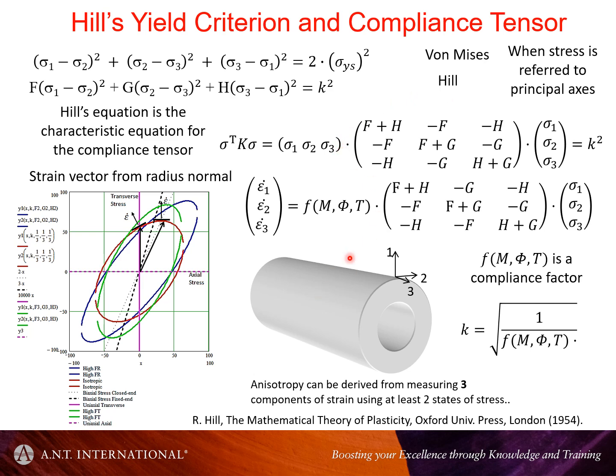And from that, we can calculate what the strain rate is, because one of the characteristics of a tensor property is that, if we're in stress space, wherever the stress locus intersects the yield surface, if one takes the normal to the yield surface, that is a value for the strain rate, for the creep, in fact.